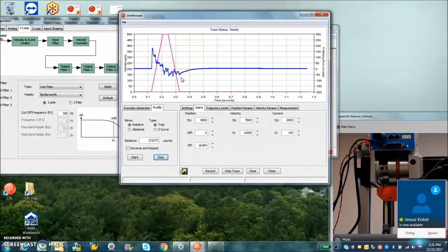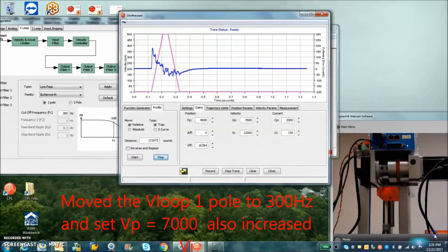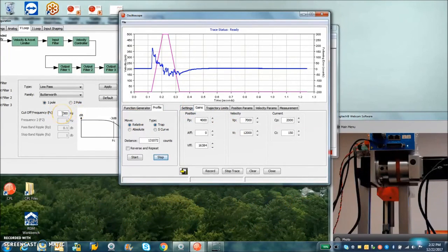So much for the 25 hertz. I think that's acceptable, as it's not a large inertia on here yet, and we get some pretty good tuning with high gains. So let's move the pole out, crank up the gains, get maximum stiffness. There's a little disturbance in there, but hey, we can see it on the frequency analysis, and we can avoid it or we can correct for it.